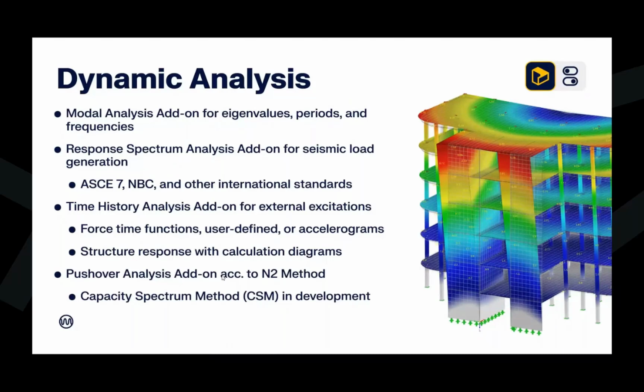So if we are interested in carrying out a seismic load generation, we would want to utilize the response spectrum analysis add-on. So within this add-on for seismic loads, we do have the codes implemented here, the ASCE 7, the NBC standard. And with the response spectrum analysis, this is applicable to any structure type. And that's why we've taken this approach with the response spectrum, because not only is this a building program, but again, we can do these fabric tensile structures, we can do domes, we can do any type of structure for which a response spectrum is applicable.